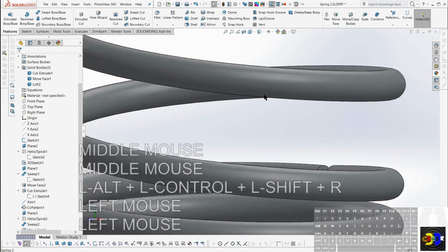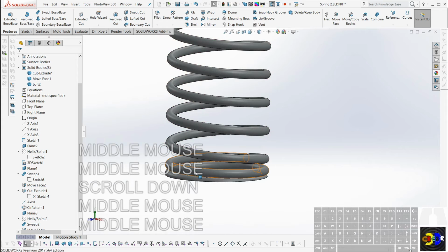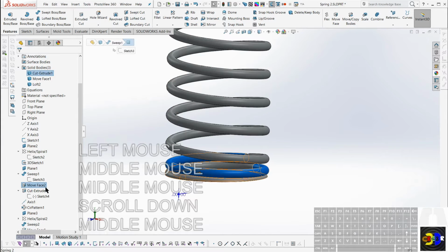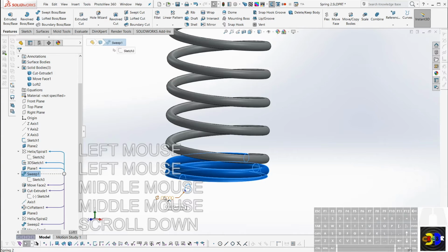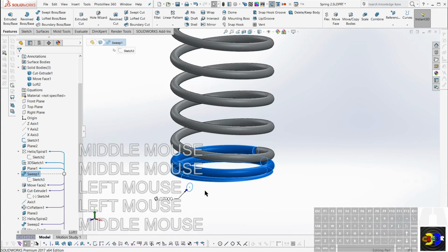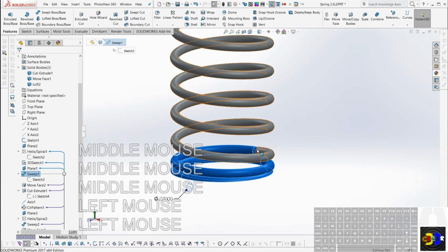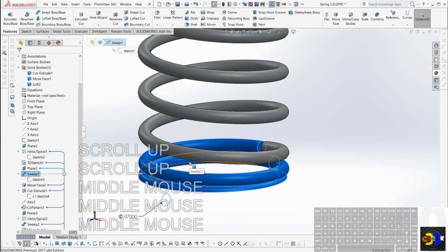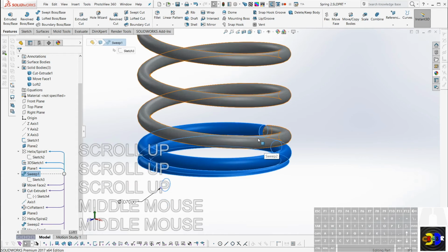So the reason I did it that way is so now we can punch in the real number. So when I put in my diameter on here, I can type in the true diameter, and the equations will work properly, and then it will just move that face slightly just to eliminate the slight interference that caused the problem.